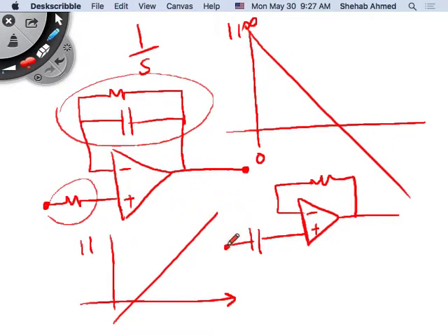Like if you have your input signal here, and your input is a square wave, this immediate rise contains very large frequencies. The magnitudes may be small, but they are large frequencies because it's something that's changing abruptly. Anything that changes abruptly, if you want to construct it using sine waves, you have to use many sine waves, adding them at the initial zero crossing. You keep adding more and more sine waves to be able to create this sudden rise, right? So that means it has very high frequency content.